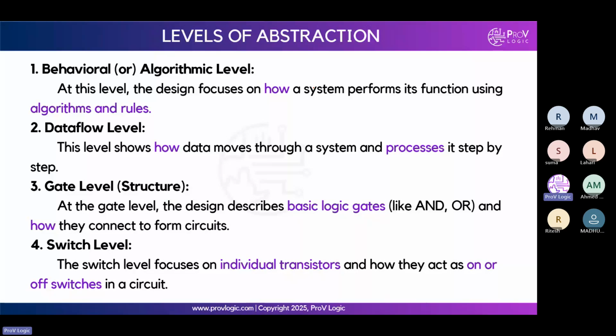In digital electronics, we follow a flow to design a gate level circuit. First of all, for whatever problem statement is given, we need to understand the functionality. After understanding the functionality, the next step is to identify the inputs, the outputs, and the control signals. Draw the block diagram based on the functionality, with the number of inputs and how many control signals there are. The clock or reset signal or any dependent signals all come under control signals.